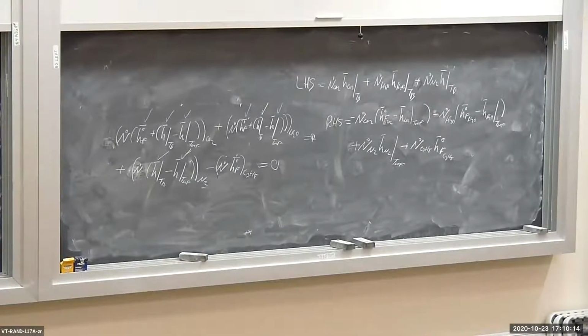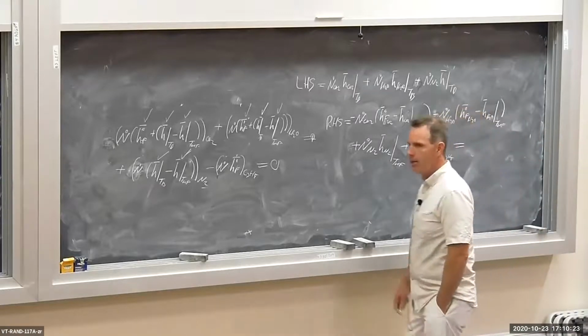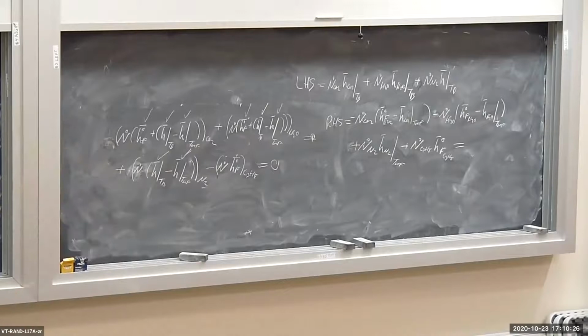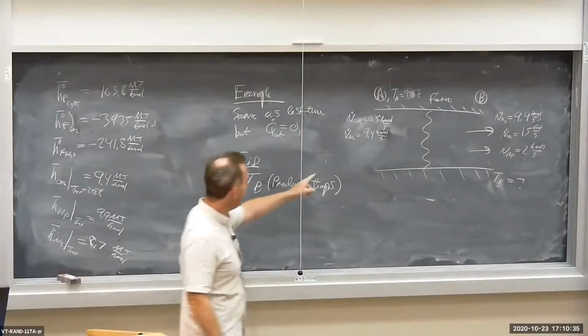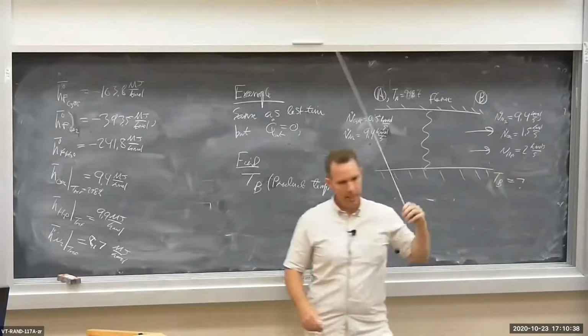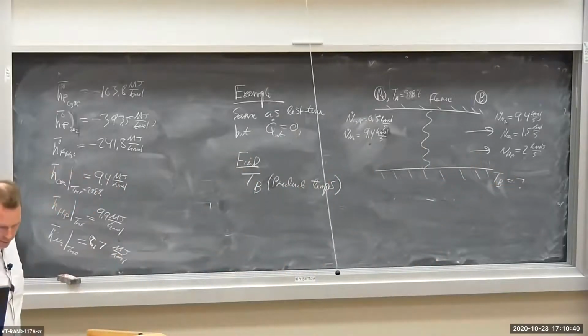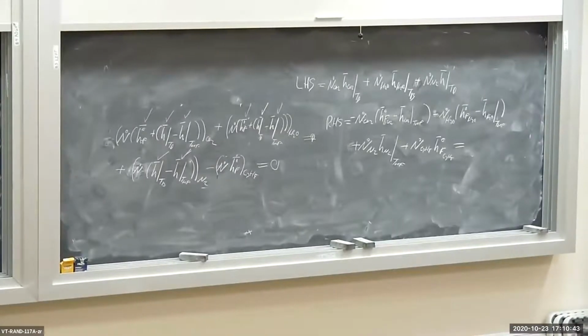All right, so everything in that equation is known: I know the N dots, I know the enthalpies of formation, and I know the enthalpies evaluated at the reference temperature. So I plug in all my known enthalpies, enthalpies of formation, enthalpies evaluated at Tref, along with the N dots, and I get 1137.4 megawatts.